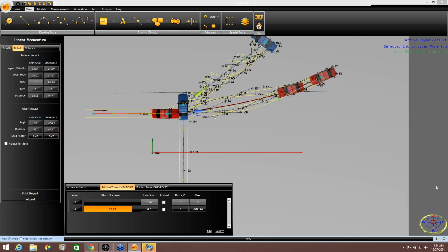What basis do you use to figure the free drag factor? So rolling friction, I guess, is what you're asking. In this case, we did a test for those cars. We took the cars over a measured distance and got them up to a speed. And then over the measured distance, what was their speed? What did it go down to? And we did a calculation to see what their deceleration rate was, just simply coasting.